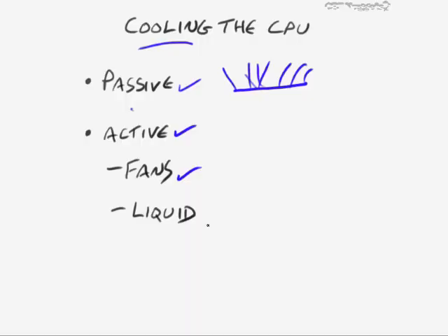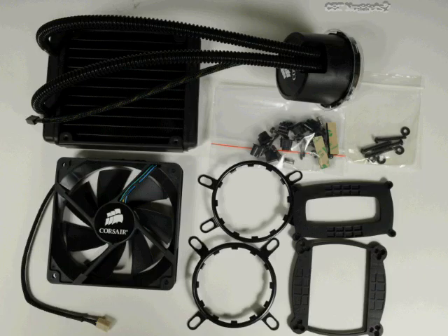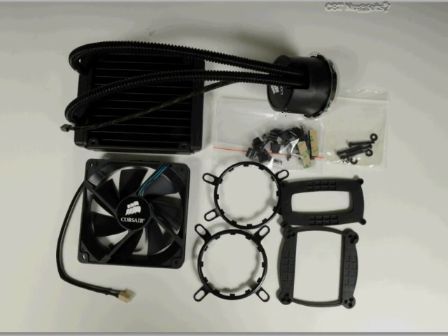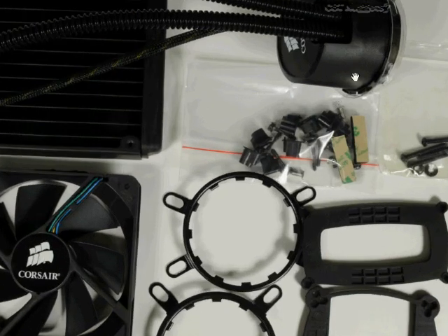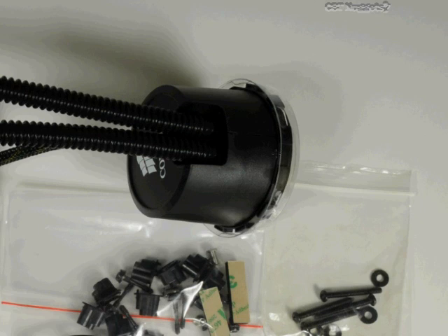And then there's also the liquid kind of cooling that you might see. That's what I'm actually using on top of the processor that I showed you earlier, that I'm using to record this video. With this one, we have a liquid-cooled heatsink. Let me zoom out a little bit so you can see it. This particular one's made by Corsair. This is actually a fan, like a radiator, that I put over one of the case locations where it can draw cool air in. There's a little screen on the front of the case, a metal mesh cage, and it pulls in cool air through this radiator, which has liquid circulating through it. The liquid circulates through the tubes here, goes into this device, which is attached directly on top of the CPU.